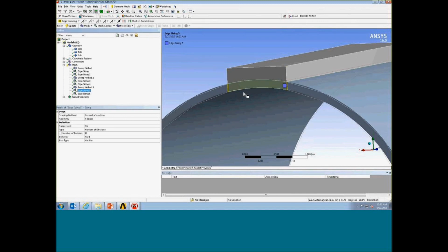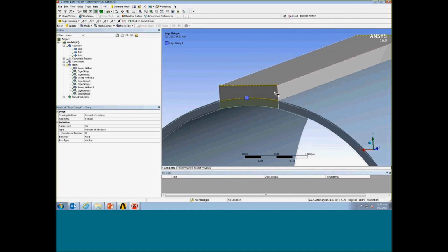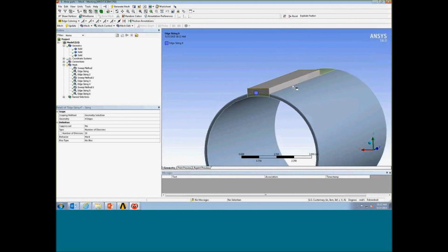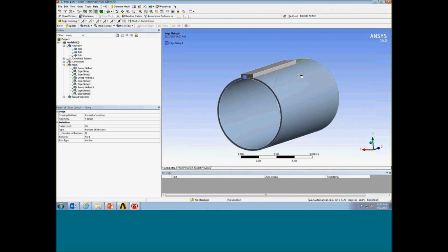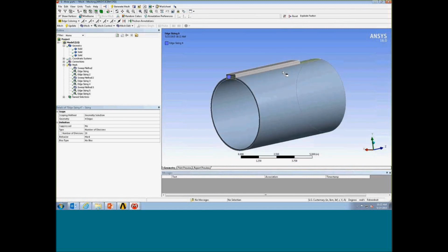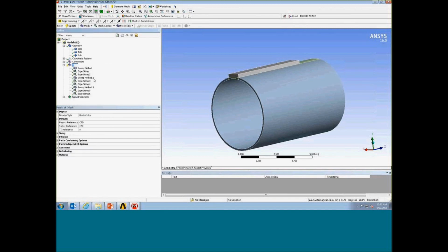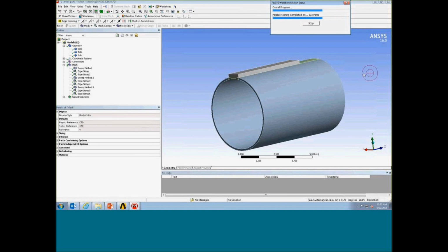And the last one will be the number of elements for the cavity in the circumference direction. So I set up in a very similar way to previously in terms of number of elements for each flow volume. And all I need to do is just right-click, generate mesh.